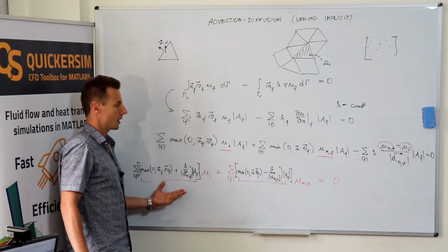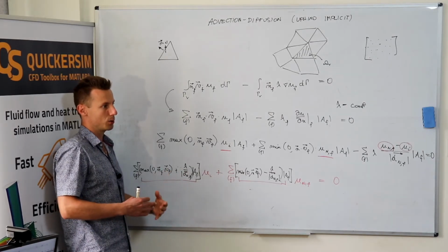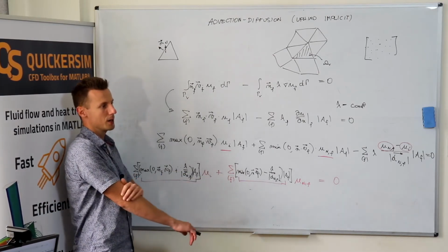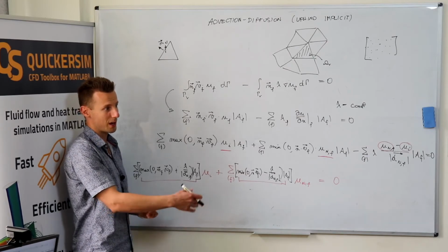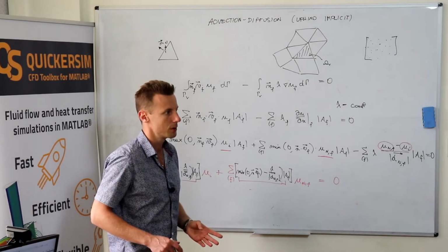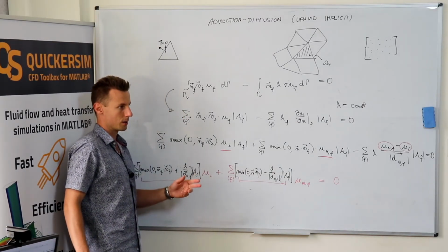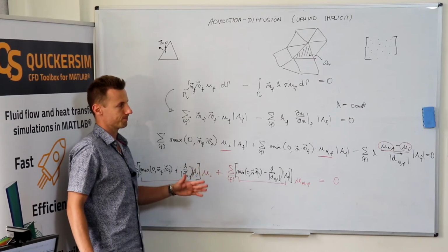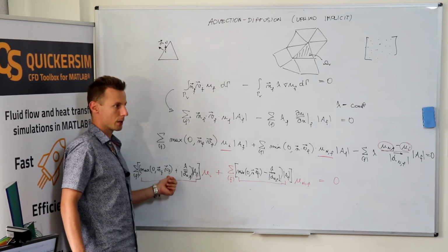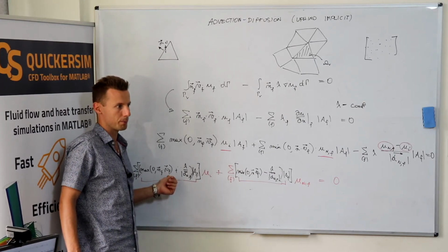Sometimes you can use some extrapolation. Let's use maybe two previous values of velocity, and let's try to extrapolate to the new solution. Or let's do some under-relaxation. I think we will be discussing things like that during our last lecture. I want to discuss some concepts like linearization, time stepping, iterations in pseudo time, etc. But generally, yes, you need to linearize that, very often taking the velocity for coefficient calculation from the previous iteration.